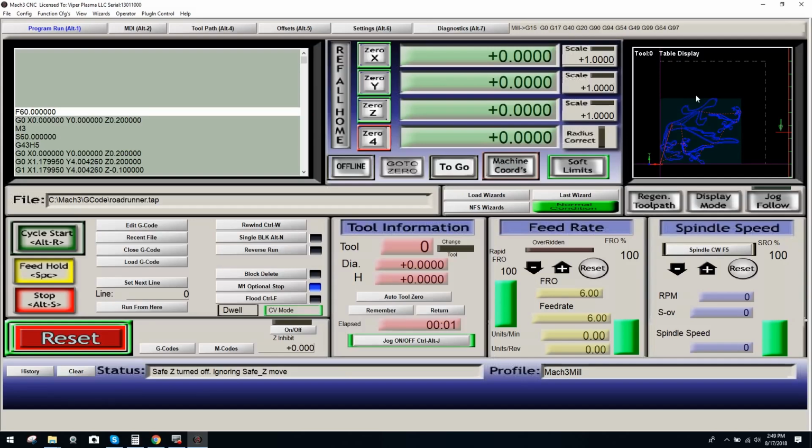You're golden. Now, a lot of guys will load a piece of G code because they're excited, and I don't blame them. They'll go to run it and think, okay, I'm set to go, everything is good, and realistically everything looks good, but what they forget is if they didn't actually touch off on the actual workpiece that they're going to mill.